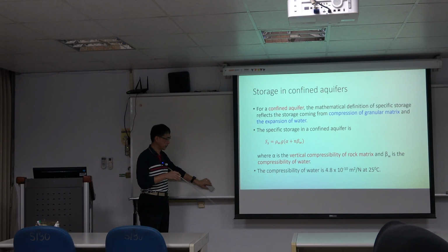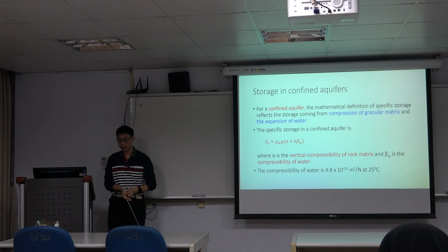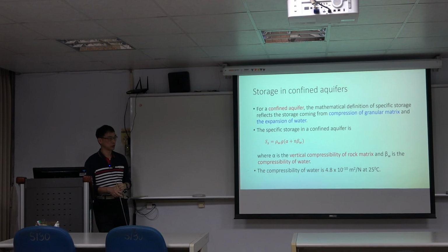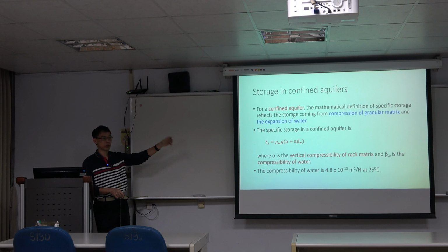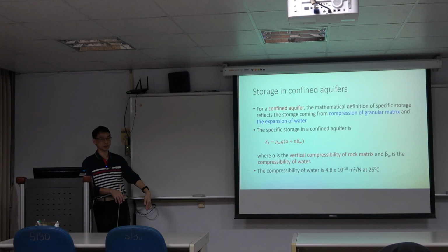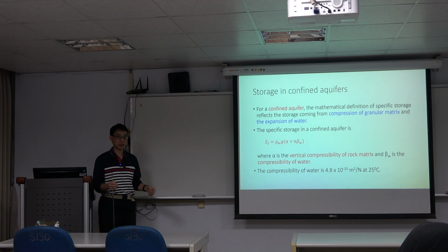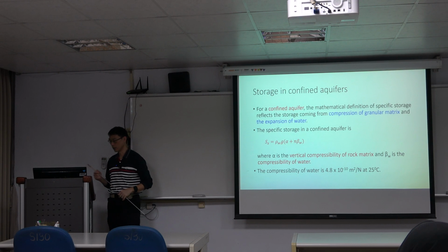This is from theory, but in reality, when you do pumping in the in situ field, at shallow depths and deeper depths, you commonly pump a lot of water. And you can see they have a decline, but maybe not so large. As I mentioned, theoretically when you pump in the unconfined aquifer, you see less decline of the head, and in the deeper confined system, you will see a large decline of the head. But in reality, maybe not. They have other influences, not only this kind of mechanism. So there are different issues here.